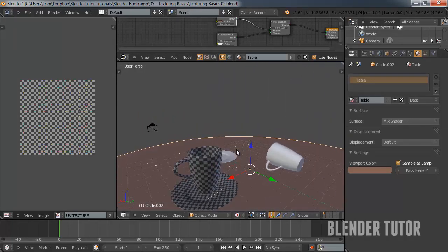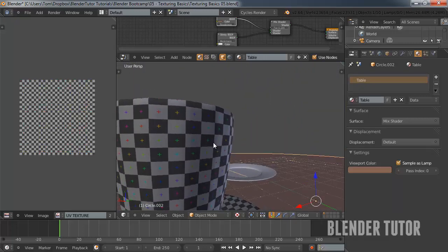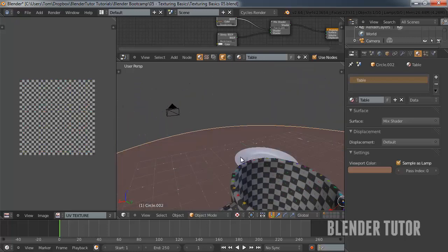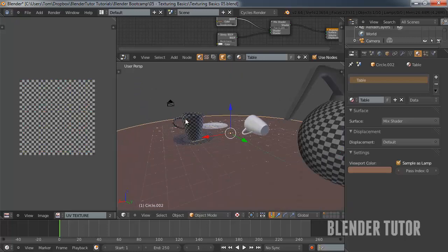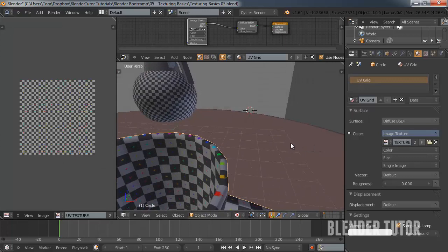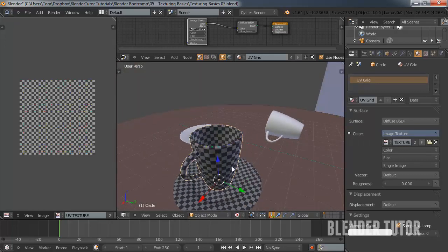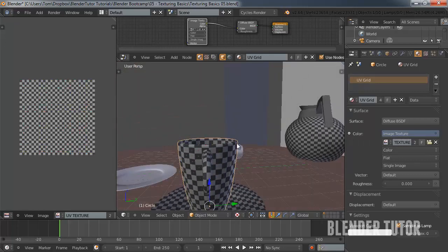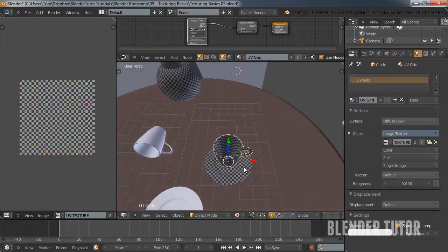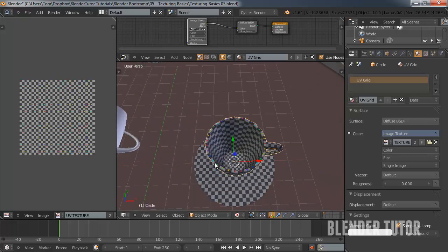Obviously, when you have a little seam, like let's look at the back here. Actually, can't really see the seam. That's not a bad job. Maybe in here. No, those are all looking pretty okay. Sometimes you're going to see a seam where the textures meet and you could see an obvious line. You're just going to do your best to hide that. Maybe do it in the back of the model where the camera won't be facing it. Like down here you could see the line right there where the texture doesn't exactly meet up. That's fine. You will want to still have it stretched out so all of the texture is pretty even size-wise.